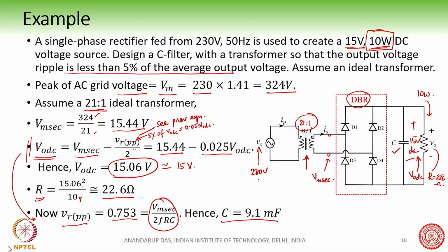The challenge of this approach is that if there is any fluctuation in the input AC voltage, the output voltage is not at all controlled. It is totally uncontrolled. So it's a crude power supply, but it will work. The other problem is that you cannot adjust the output voltage. If there is input voltage fluctuation, you cannot change the output voltage to get a nice stable output voltage.